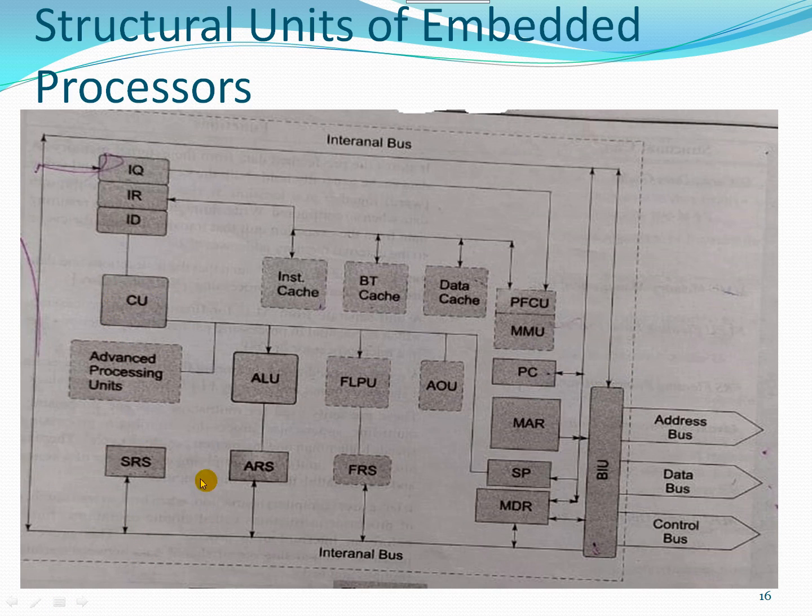Here you have this internal bus connected to these register sets. The data in these register sets can be in or out, that is, the bidirectional data flow will be controlled by this internal bus, and the data which are to be written to these register sets are supplied from the bus interface unit and from the ALU. So these bidirectional lines will be handling this kind of operations.